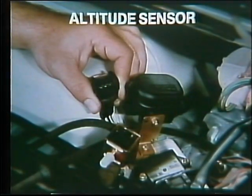In some cars, an altitude sensor causes signals to reduce fuel delivery when the air is thinner. If your car is much above sea level, the altitude sensor may be signaling for a leaner mixture.